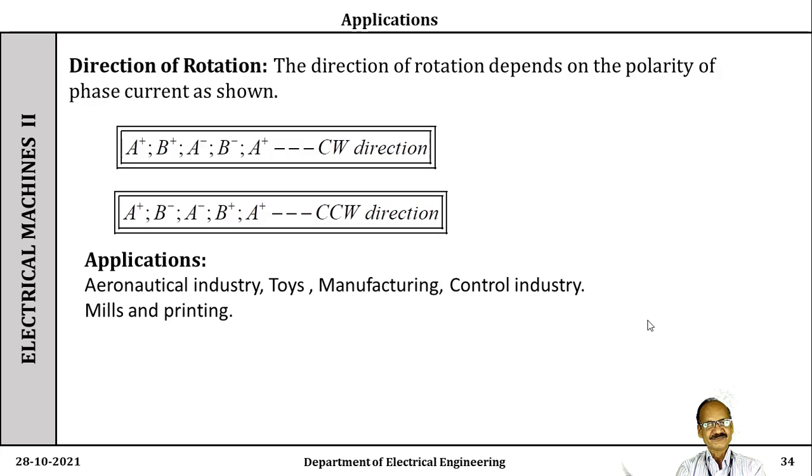However, the advantage of this permanent magnet stepper motor over a variable reluctance motor is that it has a permanent magnet rotor, no excitation is required, so power consumption is less. Then it produces higher detent torque. What is the detent torque? Detent torque is what allows the motor to achieve the next step even though the supply is off.